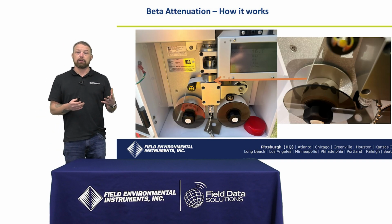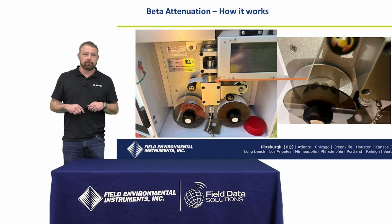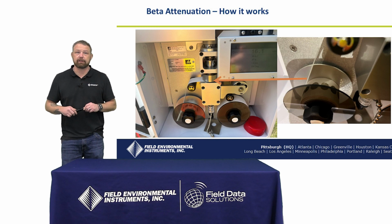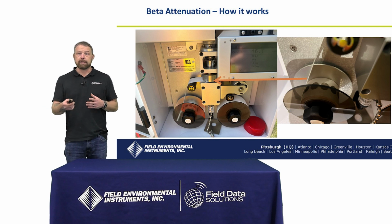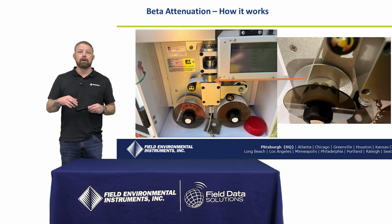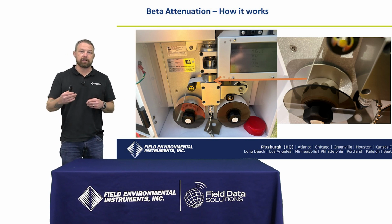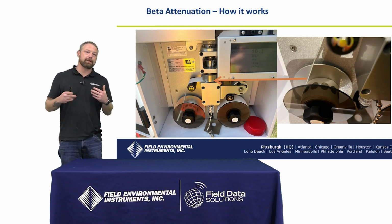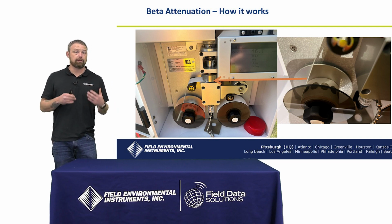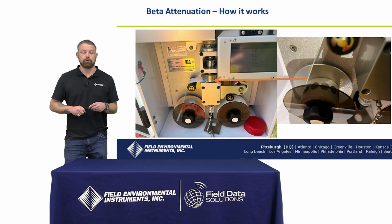Here's some examples of what the unit looks like in the field. You can see in the photos here the nozzle assembly indicated by the orange arrow. That's where your radioactive source sits. Just below that in the silver block is your detector, and between the two is your tape media. On the right here, you can see that the tape media collects the material in a circle or dot formation on the tape, and that is what attenuates the signal. The reason these are not suitable for real-time applications is because you need to allow time for that material to collect on the tape in order to cleanly attenuate the signal from the source to the detector.